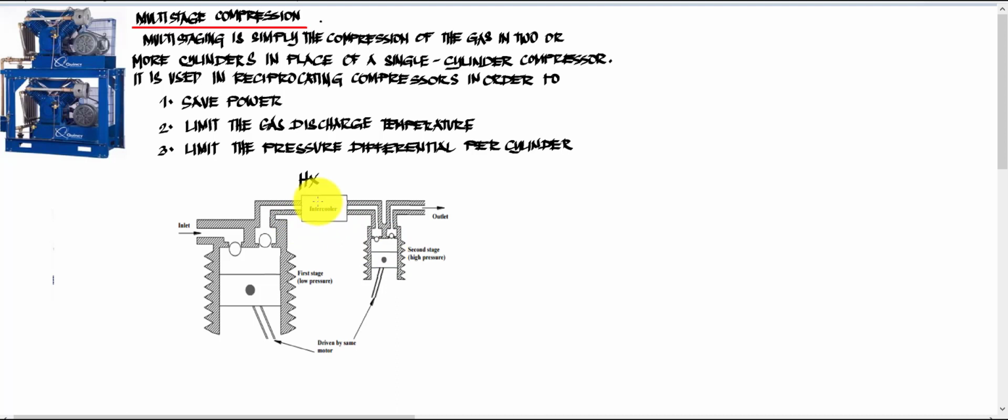Now here we have the process of heat exchanger. Here we have a constant pressure at this side. So a constant pressure removal or heat removal of the air, then at lower temperature air is compressed again at a higher pressure, and with this discharge it has a higher pressure and also a lower temperature. Comparing from here, if we do not have an intercooler stage, then this can produce a save power to the system.